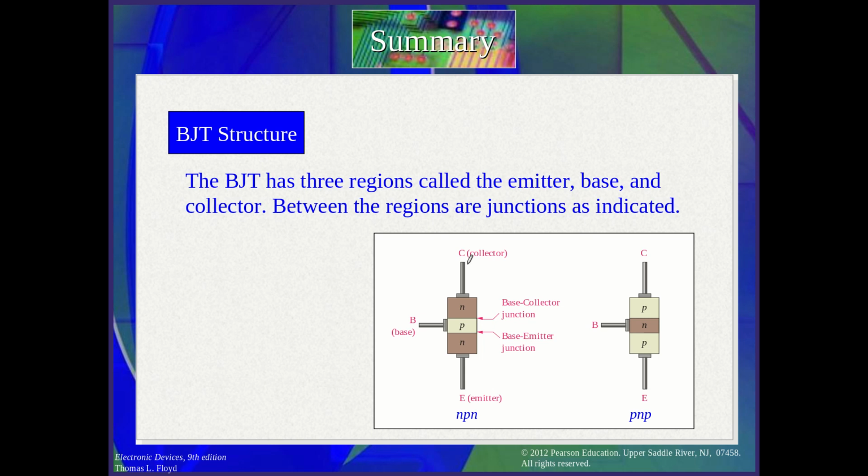We have something that we measure, a ratio between the DC collector current and the base current. So we have a state of the BJT we call saturation, where the collector current reaches the maximum value and is independent of the base current. And a cutoff region, which is the non-conducting or off state for the transistor.